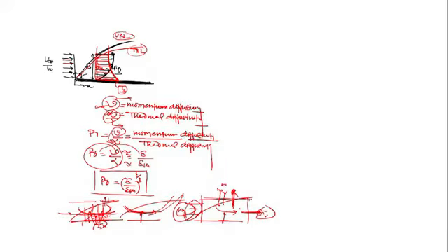Clear? So that's why bulk motion has come into the picture. Yes or no? What is bulk motion? Just like aggregates. So there is also a contribution of bulk motion, but near the surface, the heat transfer is only by conduction. But the heat transferred through conduction will enter the layer above, get swept away downstream, and finally get transferred to the bulk outside the boundary layer. Clear, beta? That's why bulk motion has come into the picture.